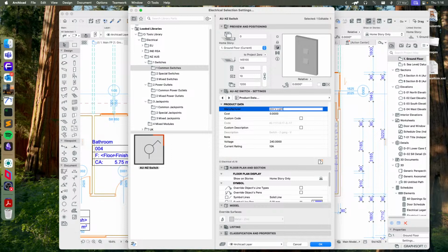And now that we're in 3D, we can also adjust the rises of these. So you can see I have some more hotspots showing on here. These work in a similar way to what we had in floor plan. So we have a middle hotspot here, which will allow us to do the riser angle. And you can probably see, hopefully, that as I'm adjusting this riser, it is moving the entire object to fit what the riser would need to do to give me the angle.